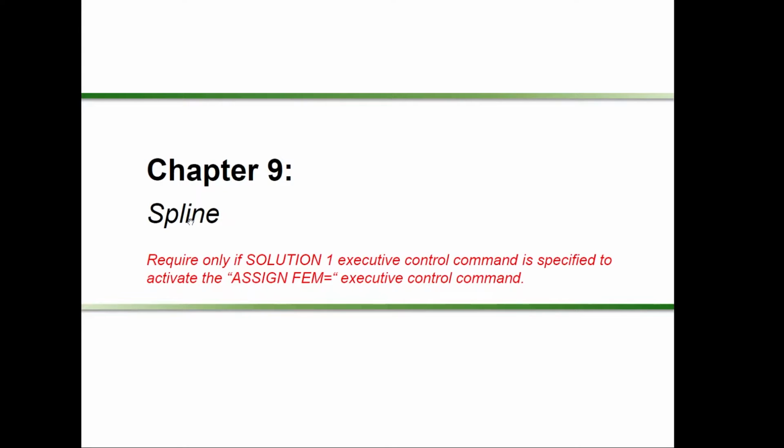Chapter 9, Spline. If we want to perform static aeroelastic analysis, including structure flexibility effect, we have to interpolate or spline the mode shape from the structure grid to the aerodynamic panels.